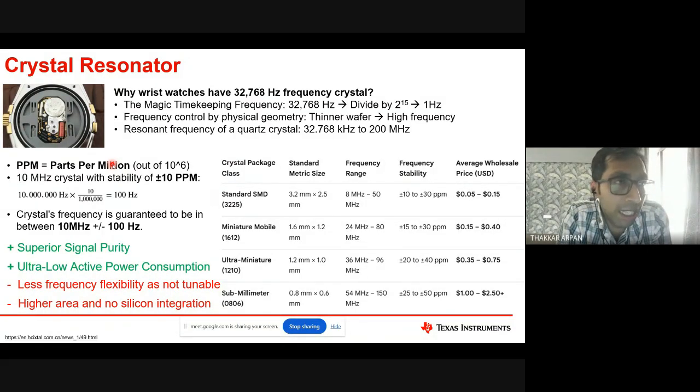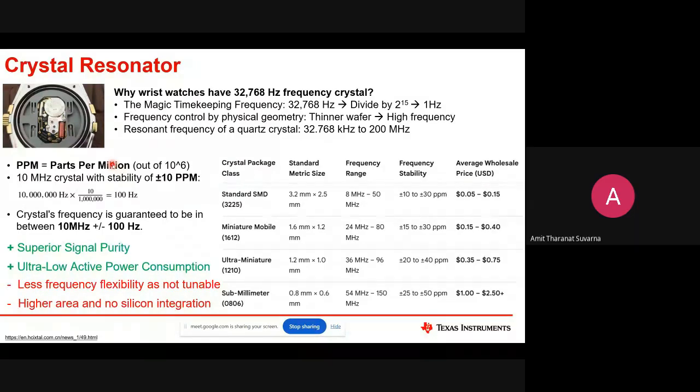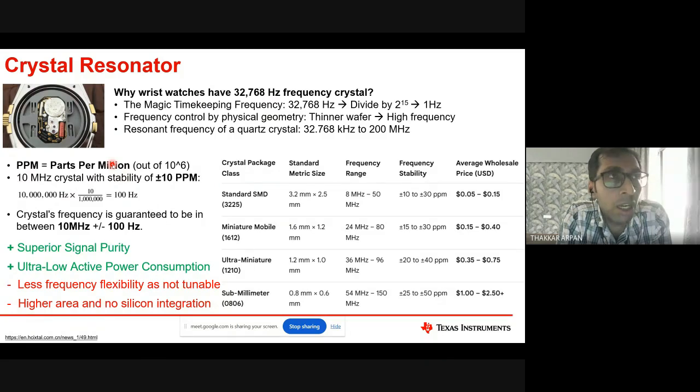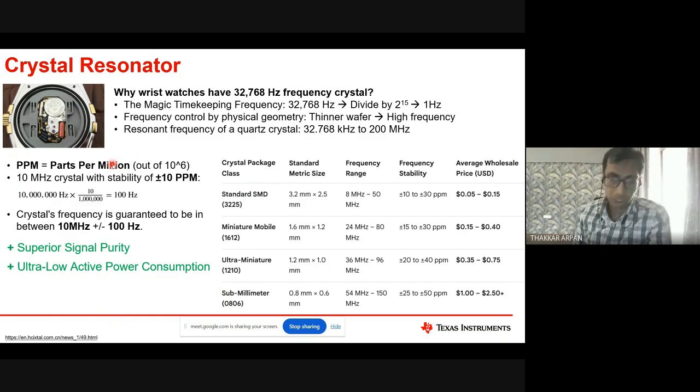They are called TCXOs, VCXOs, OCXOs. TCXO stands for temperature controlled. They will have, let's say, 25 ppm to 50 ppm kind of accuracy, and with that accuracy it can hold across temperature. Because what a TCXO is doing is it is not asking us to maintain a constant temperature. Instead, it has a temperature sensor inside and compensates for the frequency drift of the crystal.